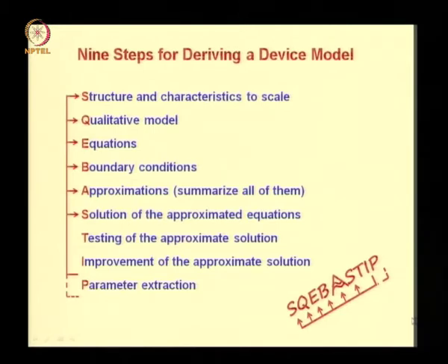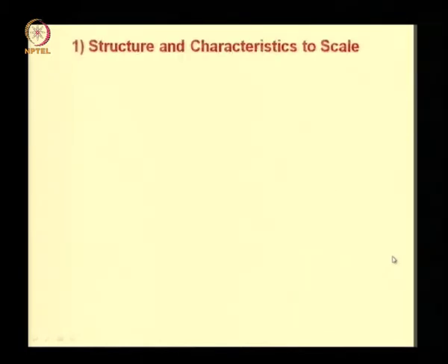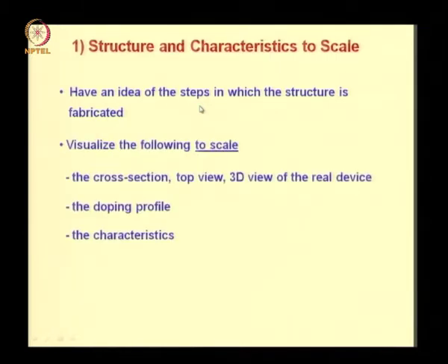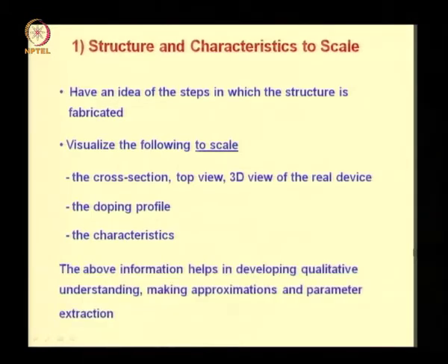So we began by specifying the 9 steps of deriving a device model, which are abbreviated as SQUEBA STEP. We emphasize that the structure and characteristics should be drawn to scale, and in this step we must have an idea of the steps in which the structure is fabricated, and we must visualize to scale the cross section, top view and 3D view of the real device, as well as the doping profile and the characteristics. The above information helps in developing qualitative understanding, making approximations and parameter extraction.